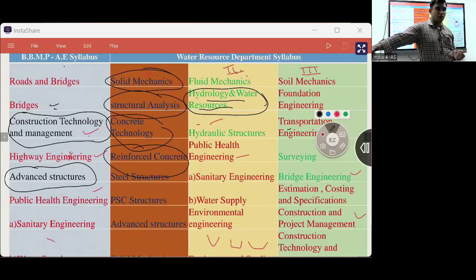So there they will find the bearing capacity of the soil, SBC of the soil, safe bearing capacity of the soil. So they will find the modulus of subgrade reaction, which is indicated by the small letter K. Okay, clear? So it is indicated by K. Clear? So this they will find.